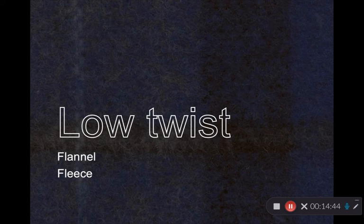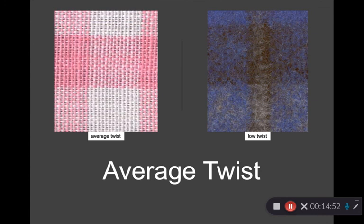Better quality yarns are higher twist that are more evenly distributed. Average twists are more compact and smooth. So you see on the left here the smoothness of that versus what you see on a low twist fabric. They are a bit more expensive, but most of the fabrics in your swatch kit probably have an average twist to them. They tend to be the most durable yarns. Filament yarns may tend to be a low twist or a very high twist. They don't sit in this average category as much. They're more on the poles. So average twist is mostly a spun yarn category.